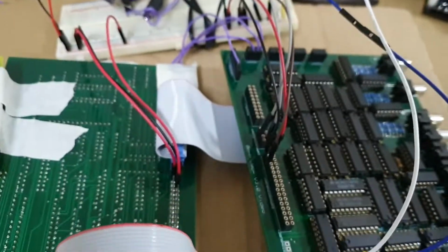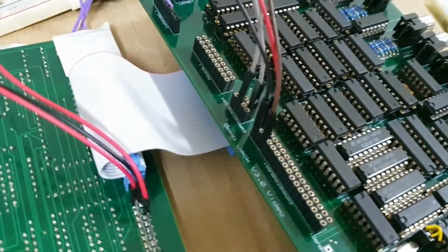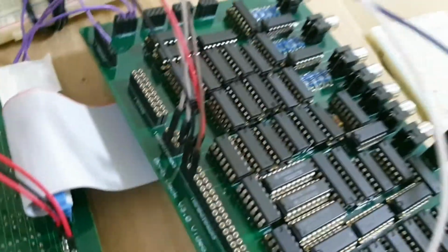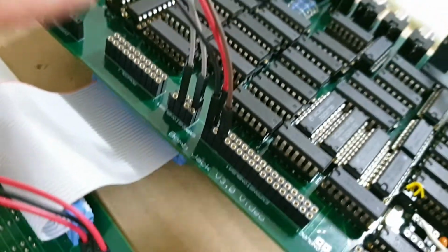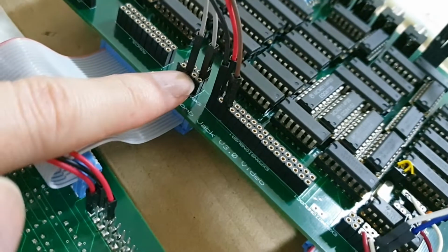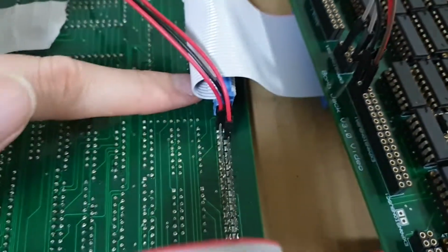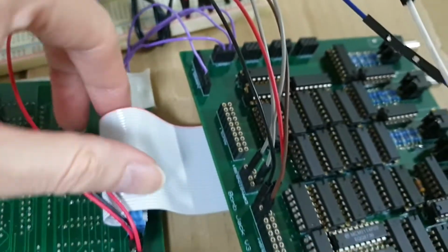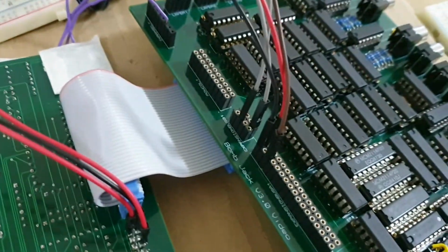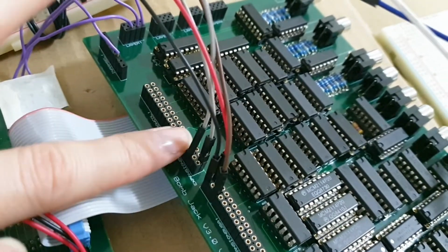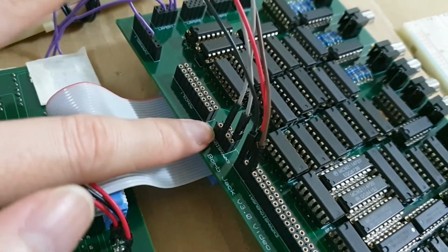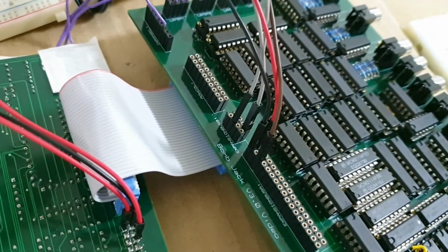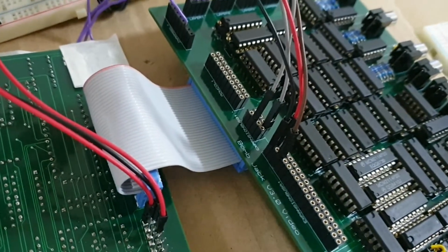The short cable is now not just across the row column header here, but actually the plug is across both the row column header and also the extended data bus header here, so the pins extend down here, of course. Likewise, for the bottom of this board, the character generation board, the pins for the extended data bus header were coming up here, and then the row column header were here. So I've used this 34-way connector to bridge both of these. Luckily enough, the headers were separated by the correct amount. Well, the PCB layout tool helped me there because the grid was set correctly. Happy accident, which is always nice.